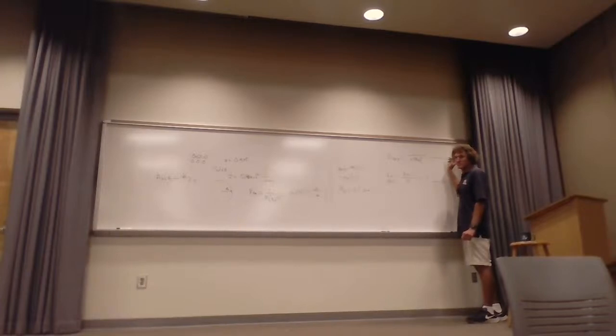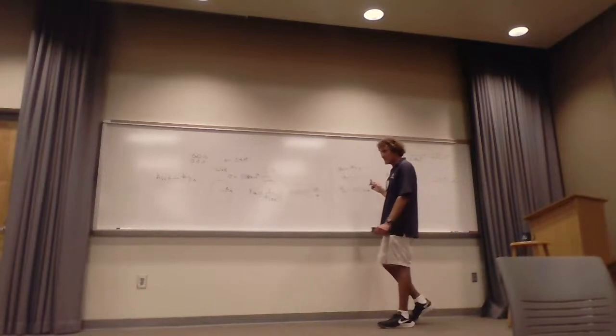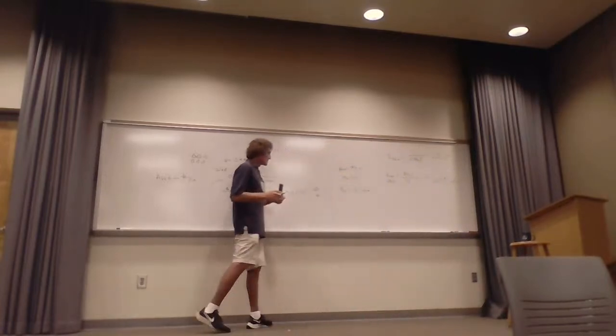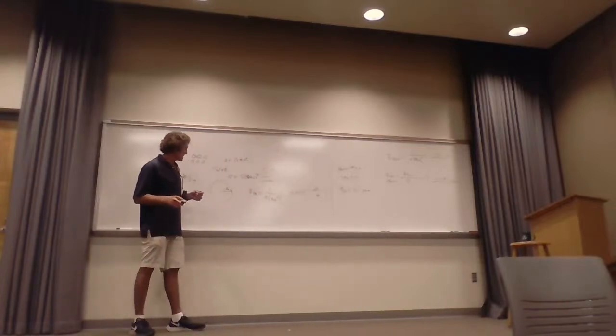What I'm getting is 1.72 ohms. Now divide that by 19. 0.09. Huh? 0.09. Yep. 0.091 ohms, right? Yes. That's what it is for 19 by 32. This is DC. Here's what it is for RDC for a solid AWG 20.